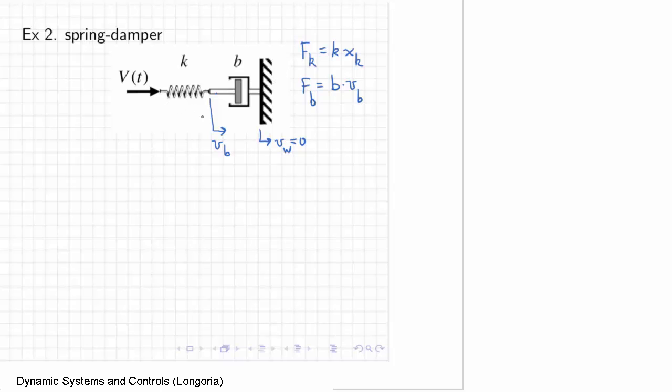Well, whatever this system is that we're modeling here, we've reduced it to ideal elements. Ideal springs and ideal dampers don't have any force, don't have any mass, so the force is transmitted across these elements and they're equal. So the force on that spring, right, is equal to the force across that damper. So we know that the force on the wall has to be equal to the force in that damper, which is equal to the force of that spring, right? So all of those are equivalent.